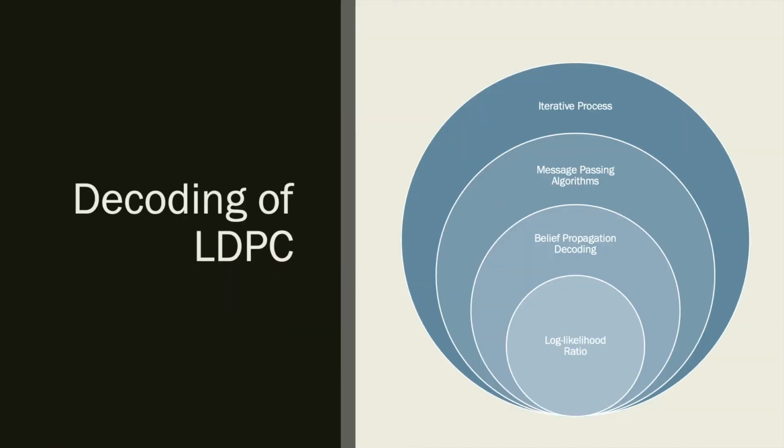The complexity of the decoding process of a code is considered to be one of the most important parameters when deciding whether the code is practically achievable. Same as the turbo code, LDPC decoding is also an iterative process. One of the most commonly used decoding methods of LDPC is termed message passing algorithms. It is named so because its operation can be explained by an iterative message exchanging process between the bipartite nodes along the edges in the Tanner graph.